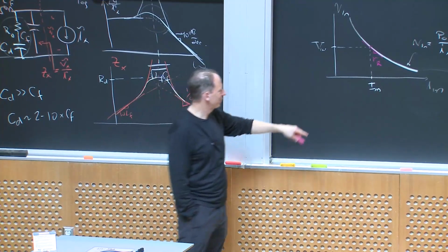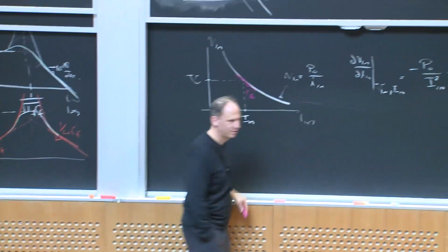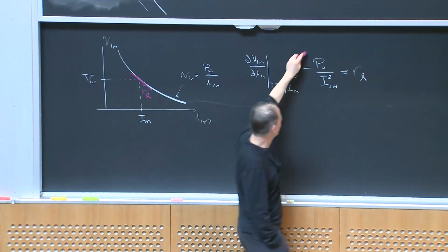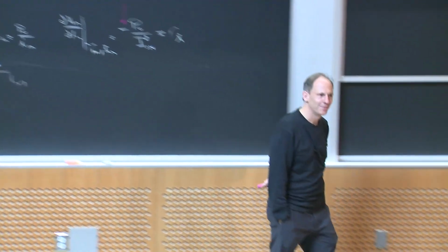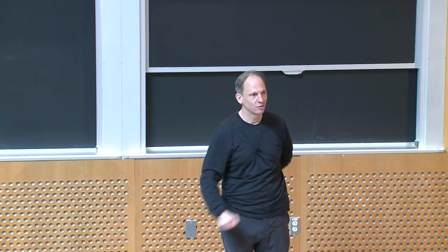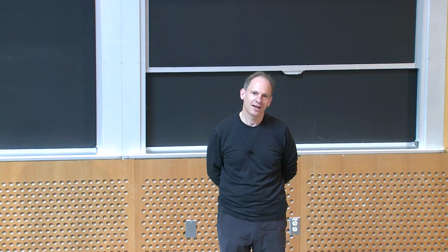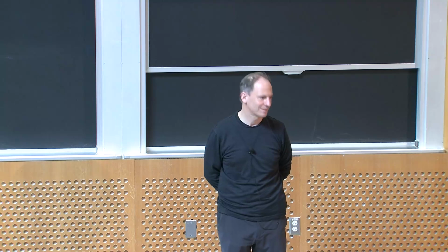Anybody notice anything about this resistance here, R sub L, this slope? It's negative. Right? So this negative sign is the source of a lot of pain and embarrassment, right? Because essentially, from a small signal perspective, the power converter looks like a negative resistance to the source. And negative resistances tend to make you unhappy because why? Because they can make things oscillate.